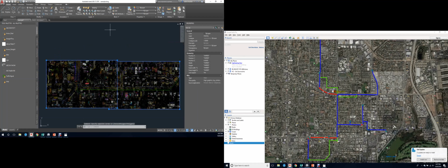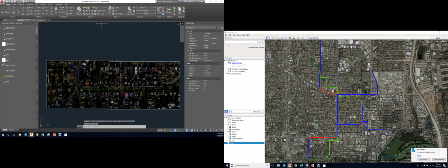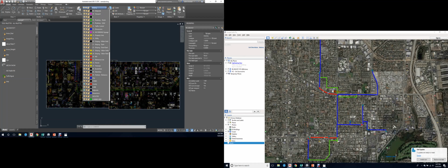All right, you want to select these, and I like putting them on the first layer up top, so I just know exactly where they are. I like to lock this layer right here. Then all you're doing here is tracing the road, the curbs, the markings, the striping, everything, right on the lines. It's going to give you a to-scale map, which is called your base map. So, pretty simple process.